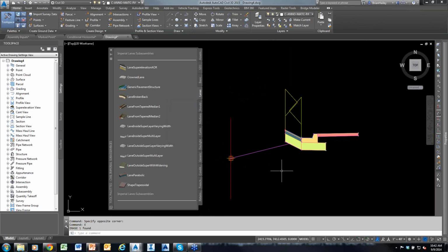So now, when I create my corridor, I'm going to tell this link, hey, I want you to target the right side flow line for offset and for elevation. And then I want you to take this lane, so this is then going to target out here. And then I want this lane to target my center line alignment and profile. So it's then going to come back and put in my lane for me. And so I now have control of all three pieces independently. I know it doesn't look good here. I wouldn't use this as a typical cross-section, but hopefully that helps you out, Sheldon.